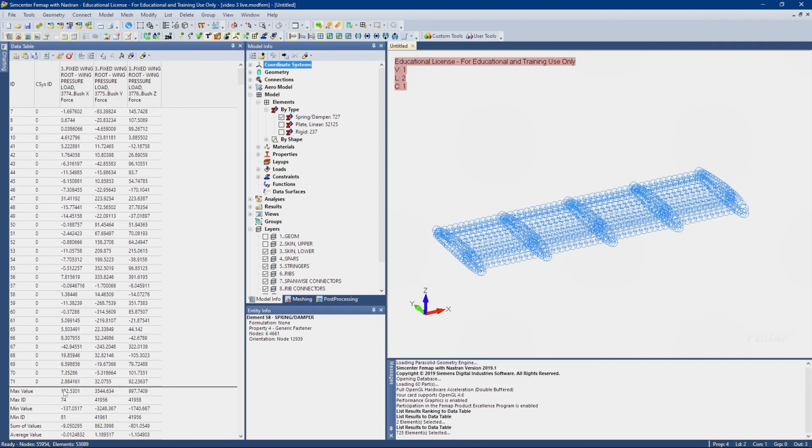So it looks like our max X is 130 pounds, which is reasonable. Our max Y is 3,440 pounds, which is pretty crazy. If these were rivets, they're probably going to be like 800 or 1,000 pounds. So we definitely have a few rivets here which are being very overstressed, and those are most likely going to be at the wing root ones.